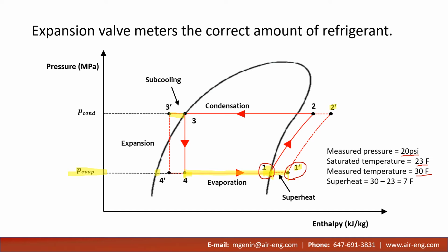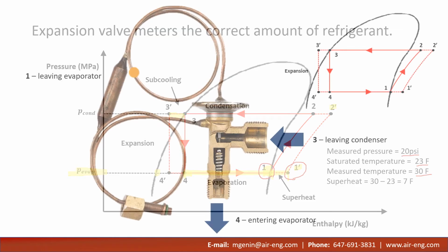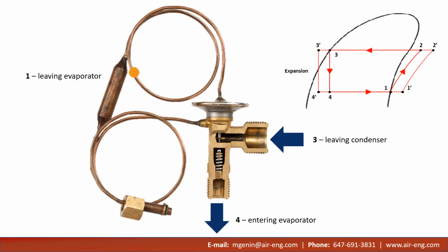Typically, HVAC systems operate, depending on the type of compressor, from something like 7 degrees Fahrenheit up to 15 degrees Fahrenheit. So how does the expansion valve really work? Some basic devices like a mini fridge just have a fixed orifice or a tiny tube that forces the refrigerant through, and it doesn't adjust. We don't measure anything. We just continuously restrict the flow of refrigerant to ensure that there's plenty of superheat all of the time. Well, this is not the most efficient method. It is certainly the most simplistic.